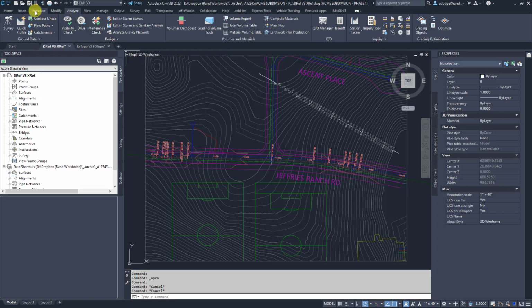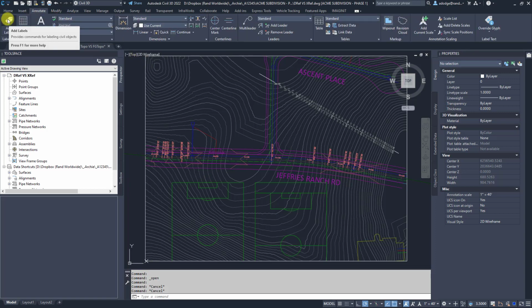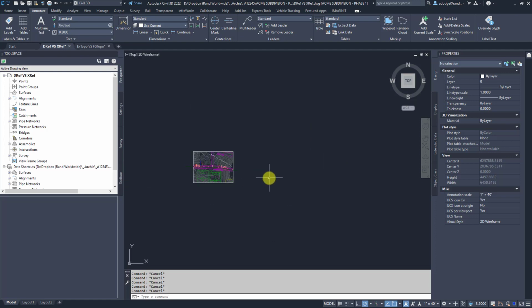And keep in mind, you do have the ability to label these Civil 3D assets directly through the reference. That right there alone should open a lot of new workflows up to you if you are not familiar with that. When it comes to showing both plan and the profiles, in that case, you may need to use a mix of your XREFs and data shortcuts.